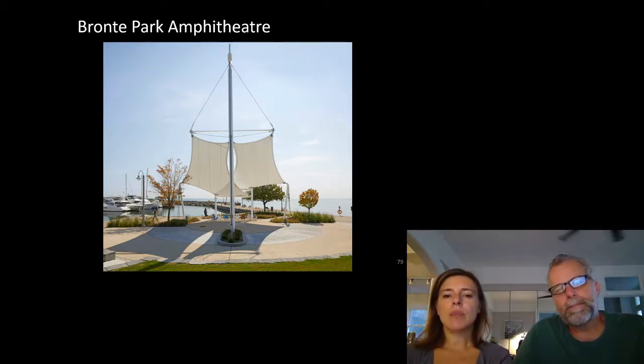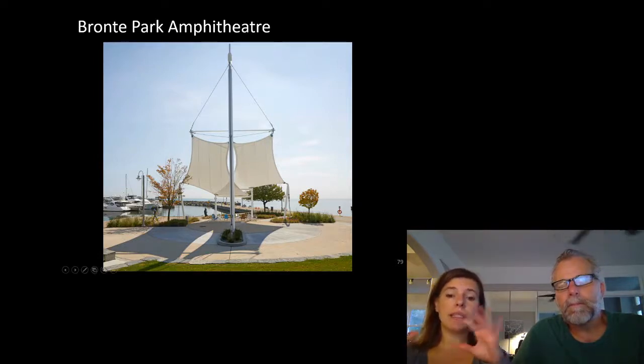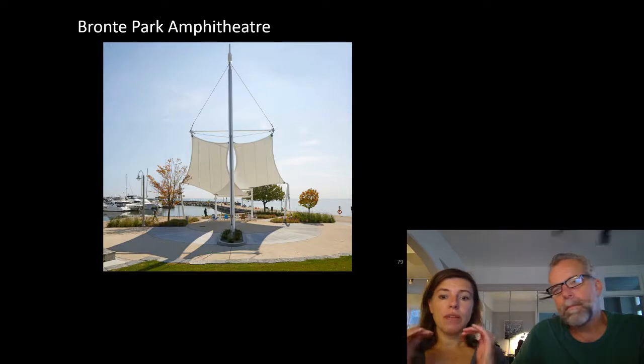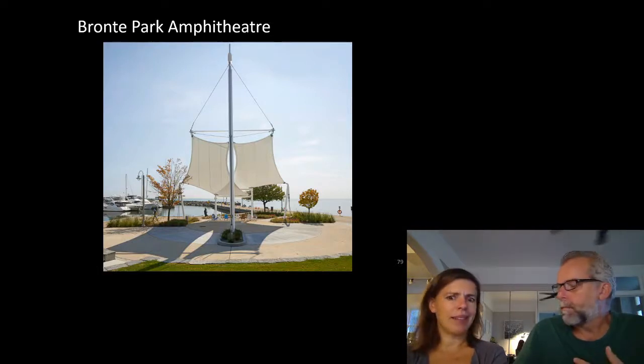That's right, yeah. So Dave proposed doing steel foundations, where this is all connected to basically a steel frame like you would see in a roof for racking, below grade. So there's a filigree of steel beams, similar to what you do with concrete grade beams, below the soil, which is what all of this is connected into. And they were able to erect that in like a day or something. The foundation went in a weekend.